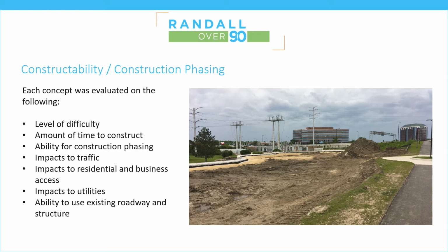Constructability. Each improvement concept was evaluated based on the perceived complexity of its constructability or construction phasing. Each concept was evaluated and given a score based on the following: the level of difficulty in construction, the amount of time it takes to construct, the potential for construction phasing or sequencing, meaning the ability to build some parts of the improvement now and others later, potential impacts to traffic, residential, and business access during construction, the possible need to relocate expensive or critical utilities, and the possibility of retaining existing pavement or bridges in the proposed concept.